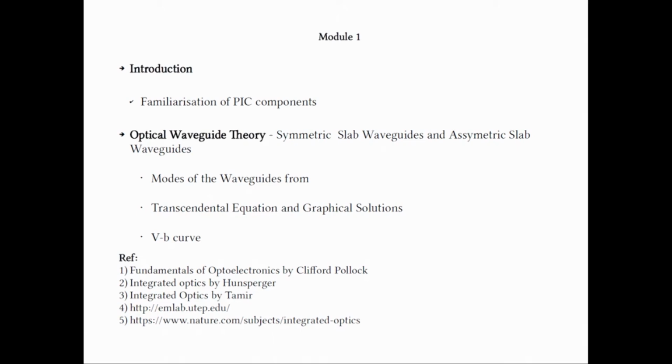In the case of the asymmetric slab waveguide also we have taken a parallel approach to that of the symmetric slab waveguide, but of course we know that it is more general, and in particular there is a cutoff V number, so to say, below which the light is not guided in the asymmetric slab waveguide. And once again we have seen several properties as a function of the asymmetry parameter and so forth. We indicated that the optical waveguide theory studied in symmetric and asymmetric slab waveguides is useful in many ways.